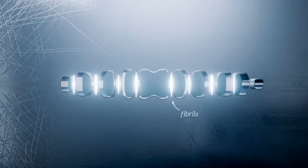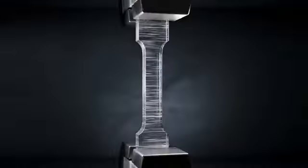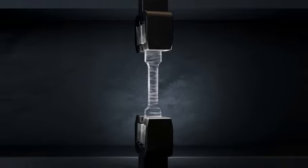These fibrils are load-bearing, and they absorb energy, which delays crack formation and propagation. If the stress continues to increase, these crazes can grow into full cracks, leading to failure. It's usually difficult to visually identify the onset of brittle failure, because it happens so suddenly. But crazing can give an early indication that catastrophic failure may be imminent.